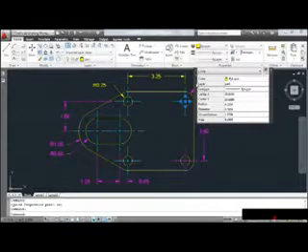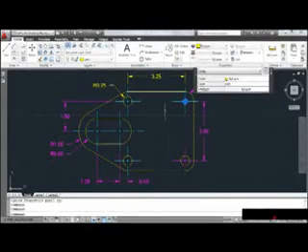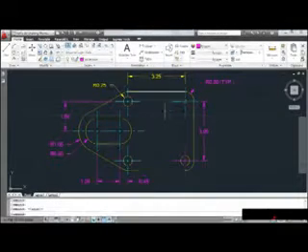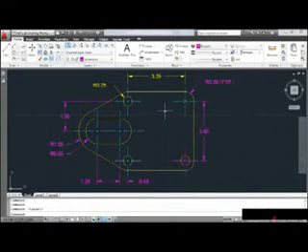As an example, I'd like to change the radius of this circle. So I'll click on the radius setting. I'll change this to 0.1 and press Enter. And when I'm finished, I'll press my Escape key to deselect the circle. And notice that the Quick Properties tool closes on its own. So by having this tool turned on, each time you select something, you get quick access to many of the popular settings.